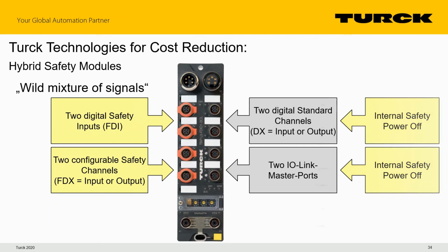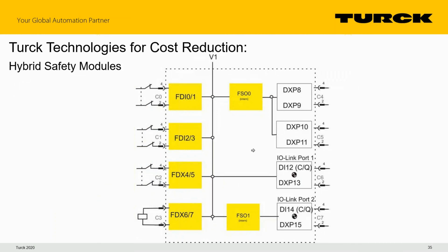And how that looks with a functional safety sketch here. Each one of these is a unique functional safety input or output. And over here, we have functional safety outputs. So I can safely remove power from these general purpose discrete I/O points. That will not be SIL level 3, but depending on your application, everything involved, it could be used as a safety function. And the same down here for the bottom IO-Link port. So that is where the hybrid term comes in.